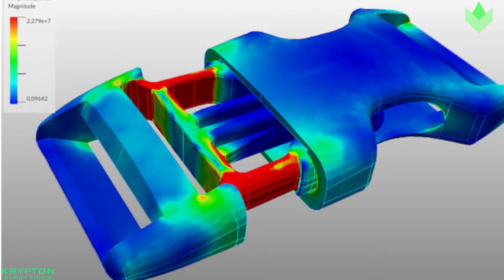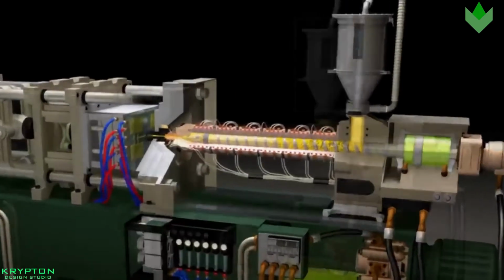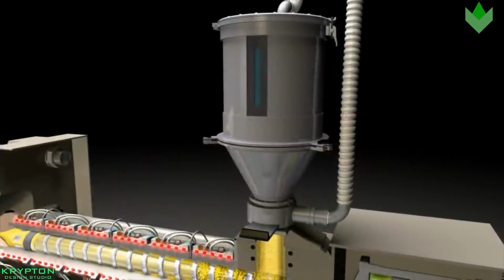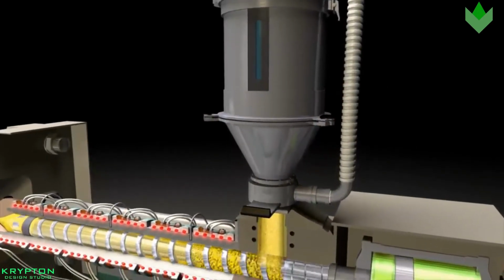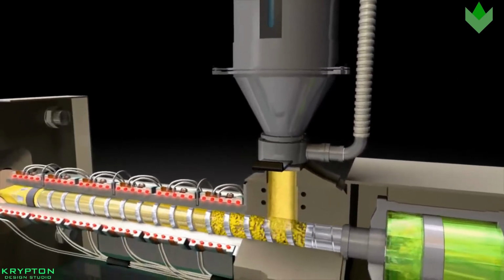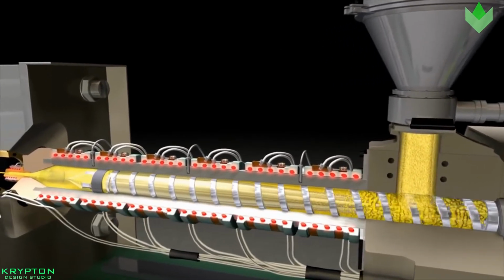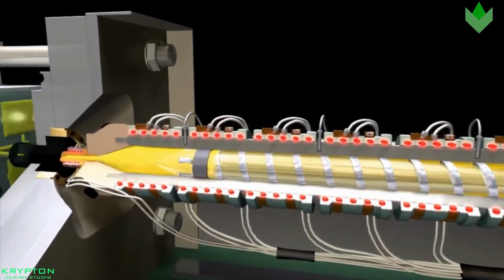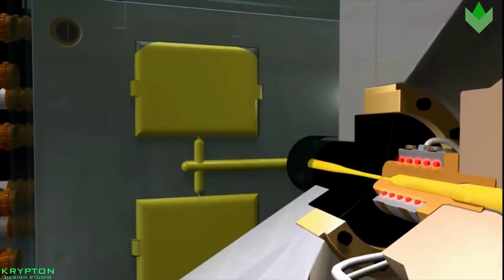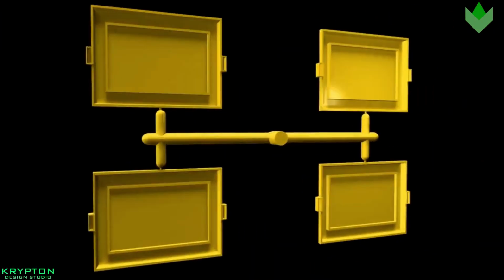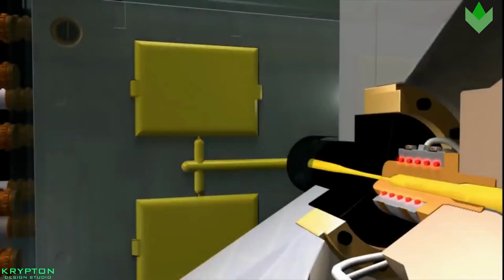Stress. The main enemy of injection molded parts is stress. When plastic resin is melted in preparation for molding, the molecular bonds are temporarily broken due to the heat and the shear force of the extruder, allowing the molecules to flow into the mold. Using pressure, the resin is forced into the mold, filling every feature, crack and crevice of the mold. As the molecules are pushed through each feature, they are forced to bend, turn and distort to form the shape of the part. Turning hard to sharp corners exerts more stress on the molecule than taking gentle turns with generous radius.